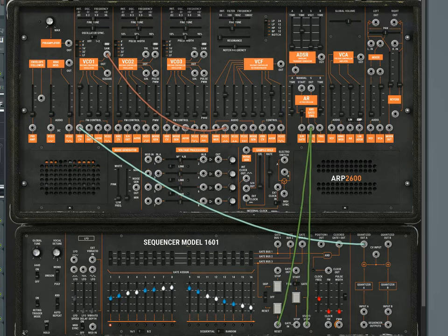So as long as I hold down the key, we hear the sequence proceeding, and as soon as I let go of the key, it stops. But the sequencer is still running. So what's going on here? The envelope is still responding only to my keyboard. So the keyboard controls whether the amplitude envelope, actually this is the attack release envelope, controlling the output volume. So even though the sequencer is still running, we only hear sound while the key is depressed.